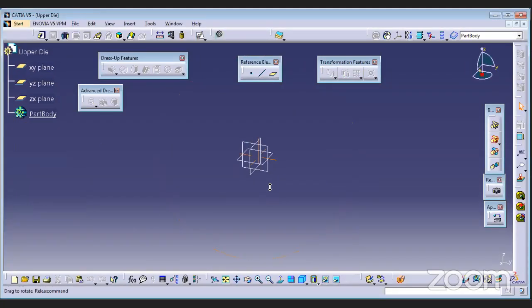And now we know the parting line defines two dies, meaning the two dies get separated at the parting line, right? So while creating a die, we have to start from the parting line, and we know that we have defined the parting line above this plane at 20 mm.